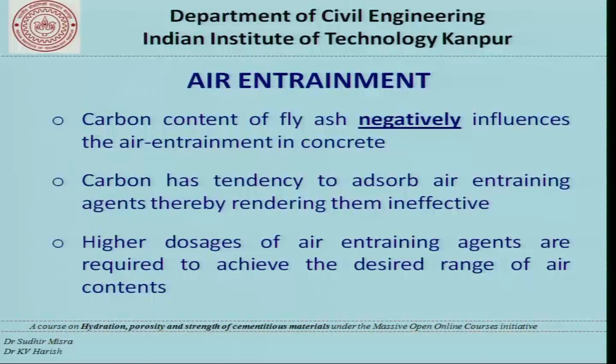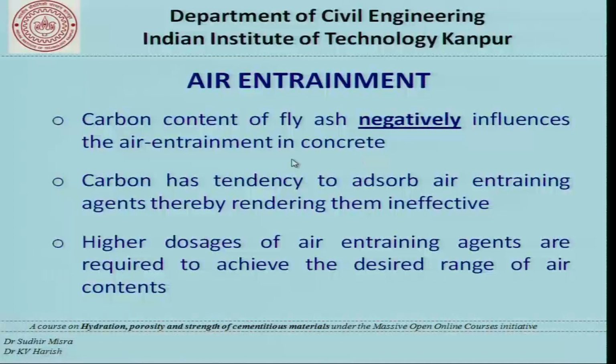So if you use fly ash, then you will require more air entraining agent compared to a mixture which does not have fly ash, because the carbon basically sucks many of the chemical admixtures, and in this case it will suck many of the air entraining agents that are present. So whatever air entrainment dosage you use for the conventional mixture which does not have fly ash, compared to that, when you use a fly ash mixture, you require more air entraining agents.